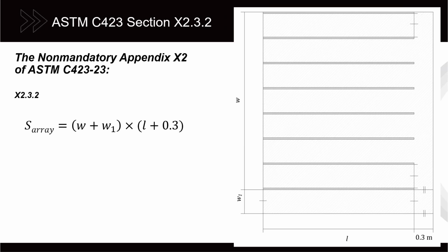So that's why most of the type J mountings don't give an airspace designation. Like let's say type D, which would be on wood furring strips, you'd have a D50 for 50 millimeter wood furring strips. But type Js in the past had always been just type J because the structure is basically suspended far enough away from any walls or the floor of the chamber where that reflection is not as critical.